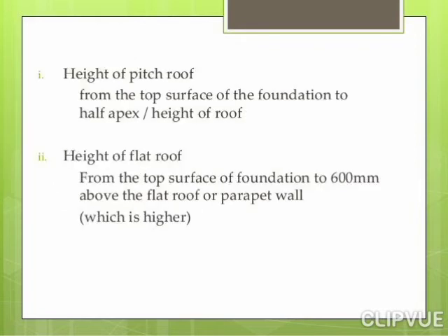The height of a pitch roof is measured from the top surface of the foundation to the half apex of the roof. The height of a flat roof is from the top surface of the foundation to 600 mm above the flat roof or parapet wall, whichever is higher.